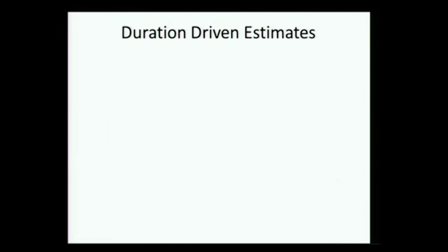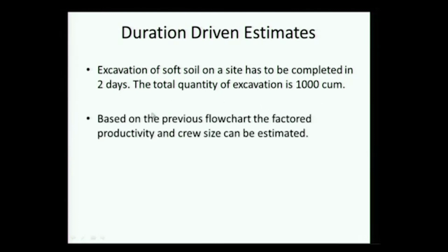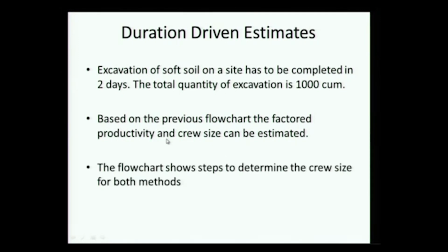If we go with duration driven, let us take an example. Excavation of soft soil on a site has to be completed in 2 days. Now we are fixing the duration. The total quantity of excavation is given. Based on what we discussed previously, we are going to try to factor the crew size.